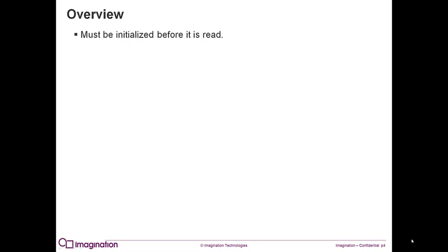Software must ensure the SPRAM entry has been initialized the same as regular memory before it is read to avoid reading spurious data. In most systems, the BSS section is cleared when the processor is being initialized or the process is first brought into memory. So if you configure your data Scratchpad after this clear step to the address that covers the BSS section, you will need to clear the area again.